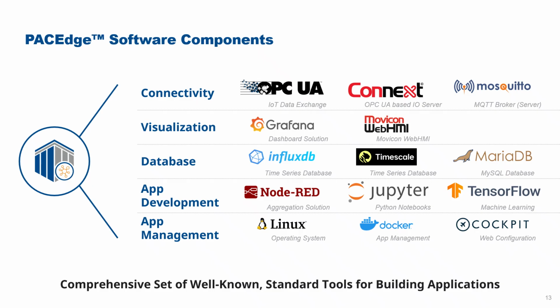For people that want more of an OT type solution, more of a traditional HMI SCADA, then that's where Movicon Web HMI comes in. Movicon Web HMI is an optional extra, but this gives you the ability to create more visualization in terms of a standard HMI SCADA or operator interface. So you can draw pictures of the machine, you can animate those pictures based on real time and the historical data. And what you can also do with Web HMI, you can quite easily create set point actions. So a local operator could write data back to the PLC or the controlling device to perform control actions. Now, Grafana can do that to some extent, but it's probably easier if you're going to do a lot of control to use Web HMI.